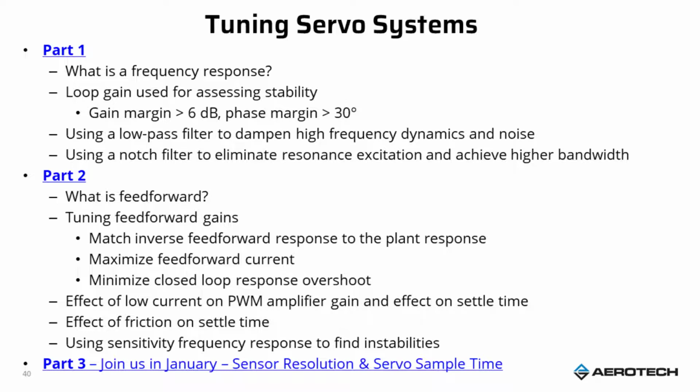So thanks very much for attending the webinar. I hope you found this information useful and you can apply this in your everyday life going forward. What we covered today was tuning the feed forwards, and we looked at 3 different techniques for doing that. We looked at 2 different nonlinearities, in terms of amplifier gain at low currents and what friction looks like, and how that affects the systems, and 2 small things that we can do about that.